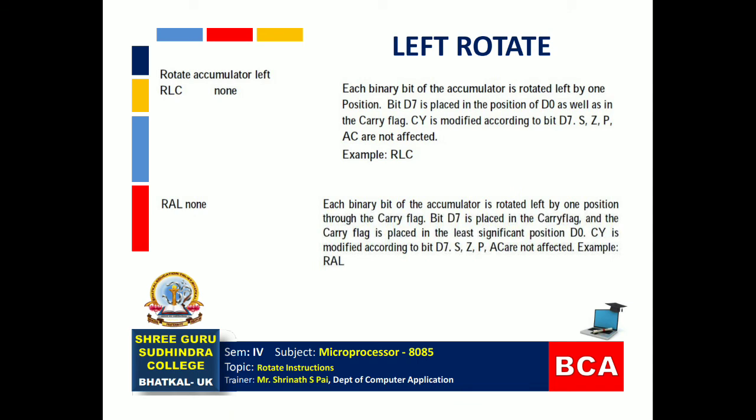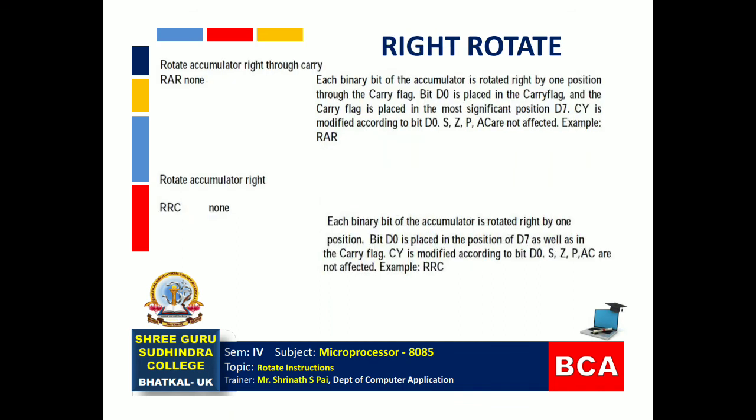So in this session we have discussed four instructions which are divided into two parts, left rotation and right rotation. Under left rotation we have discussed two instructions, rotate accumulator towards left and rotate accumulator towards left through carry. And in right rotation category we have discussed two more instructions, rotate accumulator towards right side and rotate accumulator towards right side through carry, with and without carry.